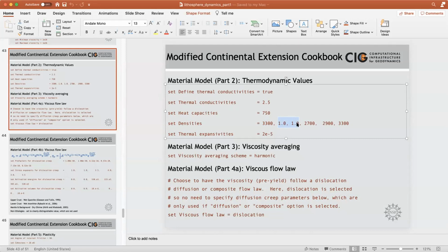And so these values actually don't matter. These are fields which are just tracking the strain, which modify the lithologies, but they're not lithologies themselves. So we could set these values to anything we want in theory. I don't think you want to set them to a negative number because that could potentially lead to some weird issue somewhere in the code. But typically I set these to some characteristic value like 1, just to remind myself these values are not lithologies, but are associated with the plastic strain. And then here we'd have the values for the upper crust, the lower crust, and the mantle itself.